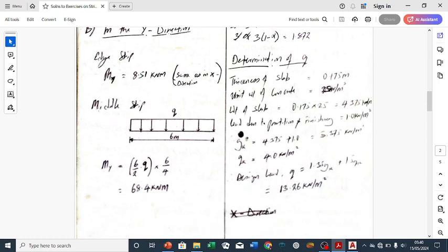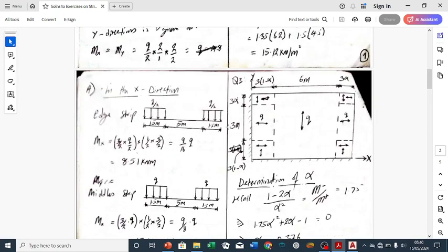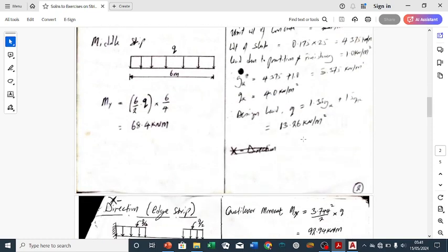But now the middle strip in the y direction is where things will change. So in this direction at the middle strip, the load acts across the entire span. So when you come here, that's why you have the Q acting across the entire span. And so what do? Half of this load will rotate at this edge, half will rotate at this edge. So what you need is just to calculate the load at one edge.